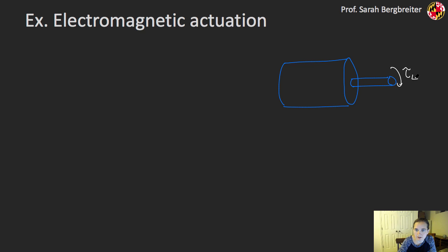That would be some load torque, basically. So it'd be trying to rotate something, for example, and that would provide the load torque as well. But this would also have some speed associated with it, omega as well. So those are kind of the two outputs of my motor, the torque and the speed. Now, as we'll talk about, I can actually represent this motor by this fairly simple model here of a resistor, an inductor, and a voltage supply all in series. So this equals this model here.